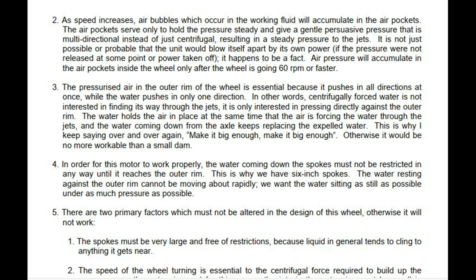4. In order for this motor to work properly, the water coming down the spokes must not be restricted in any way until it reaches the outer rim. This is why we have 6-inch spokes. The water resting against the outer rim cannot be moving about rapidly. We want the water sitting as still as possible under as much pressure as possible.